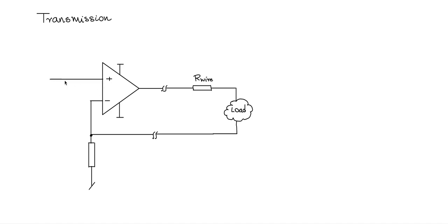And here from the transducer you have a voltage which comes from the output of the transducer, and that voltage is passed through a zero span circuit to get VT, which is proportional to whatever the physical parameter that is being measured by the transducer. Now the operation is as simple as this. What does this do? So let's say this is plus.